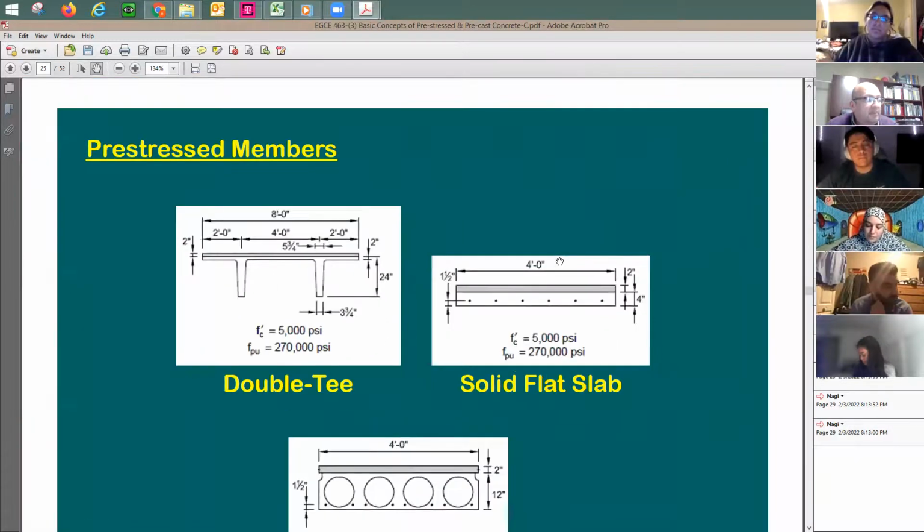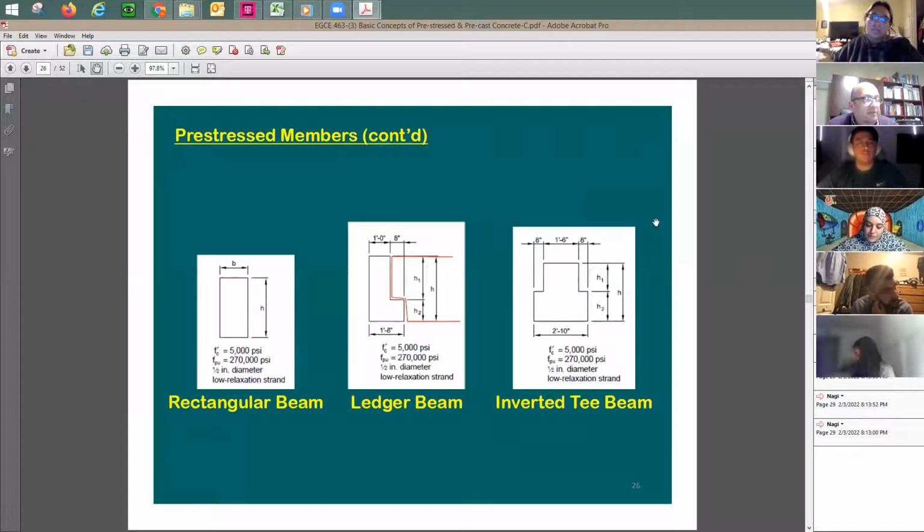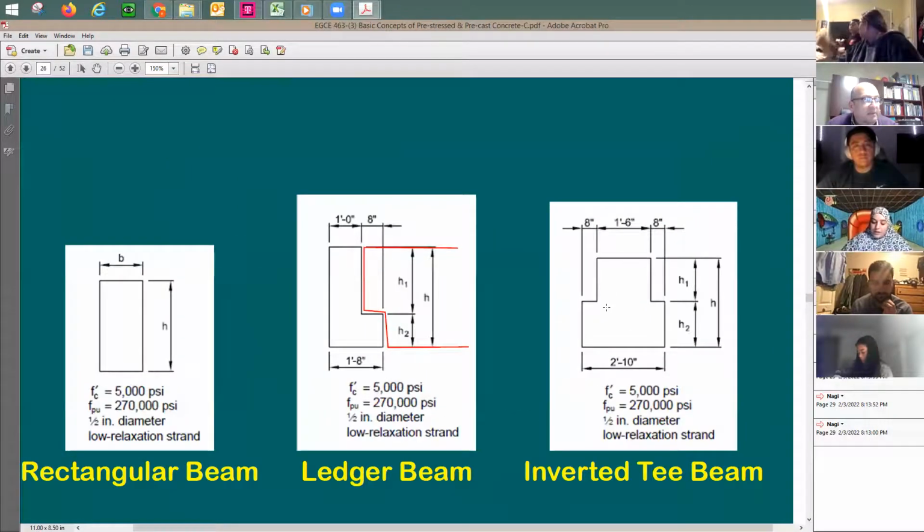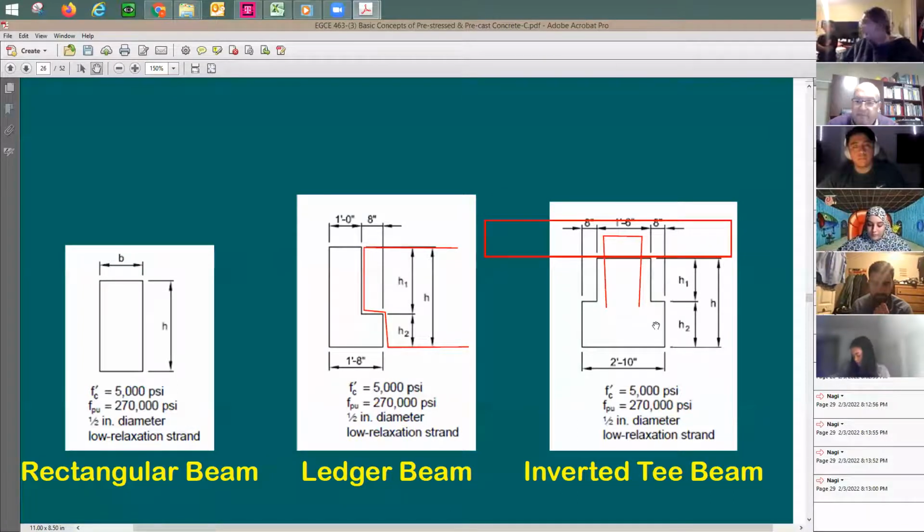But in bridges, it's going to be completely different. In bridges, let's say that you're going to see here a rebar, and the rebar is going to be coming like this, embedded inside the concrete beam itself. And then you're going to put here a concrete slab that you want to be working as an integral part with the beam. So in a case like this, you need to put all of these dowels. It's going to be conventional rebars, and all of these conventional rebars in bridges are usually exposed, so they are epoxy coated. Got it.